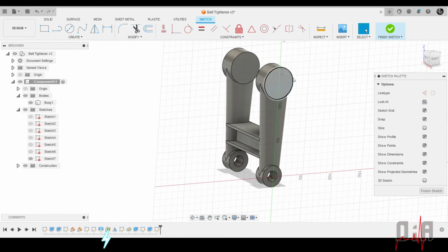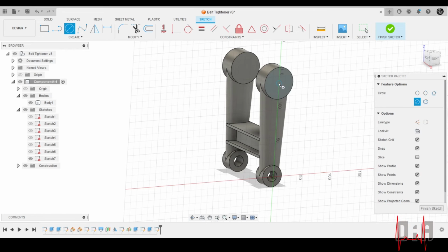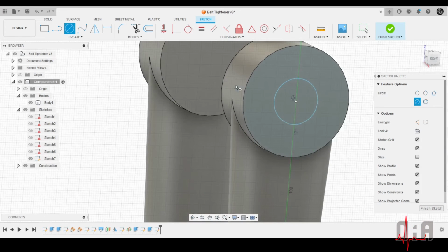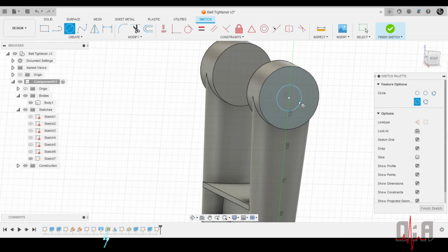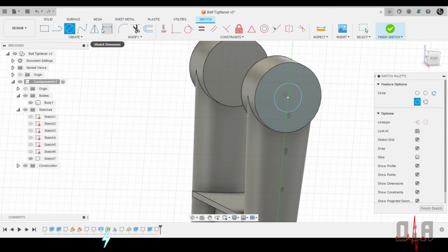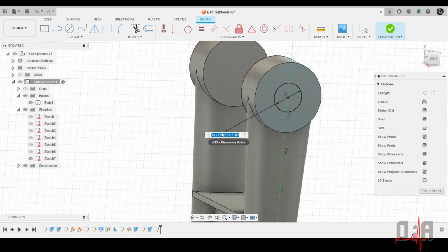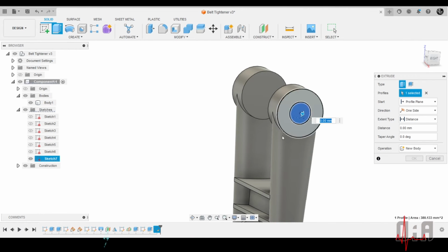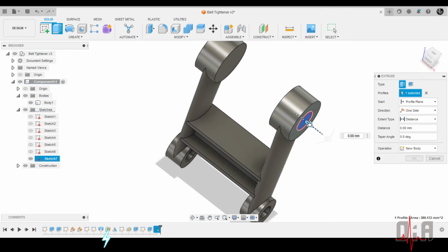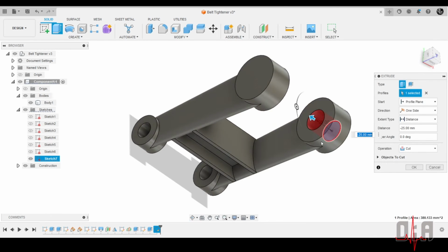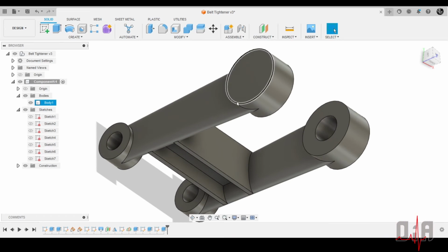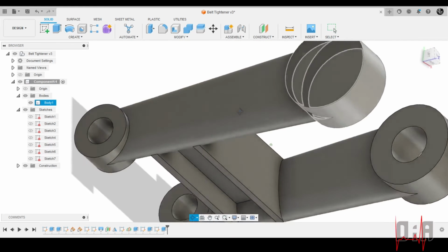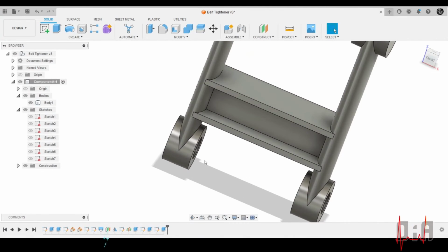Okay, so I picked this face for this one. Now, say you don't find the center, you can easily project and you get the center of the circle. Well, in this case, it's better. So this is a diameter of 22. Based on one of the models I saw, the one I'm using particularly, that one has a keyway as well as a similar diameter to this.